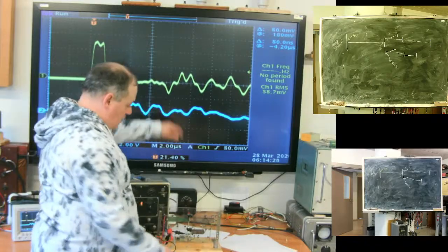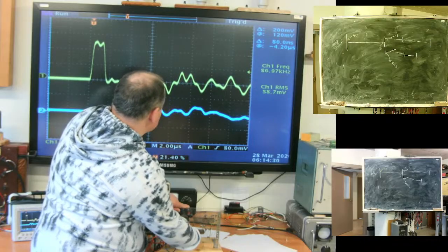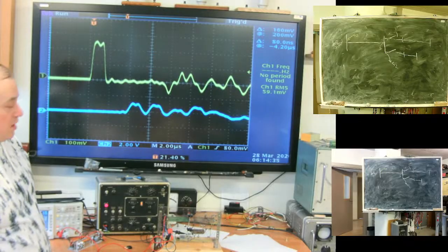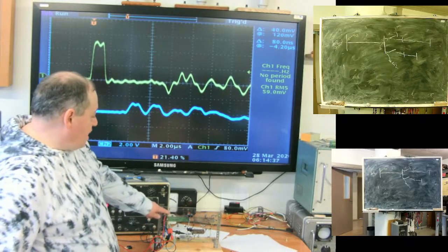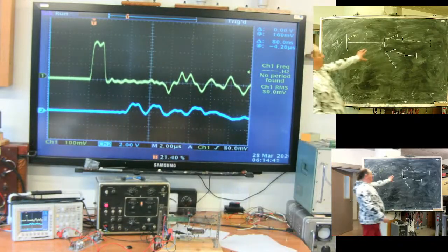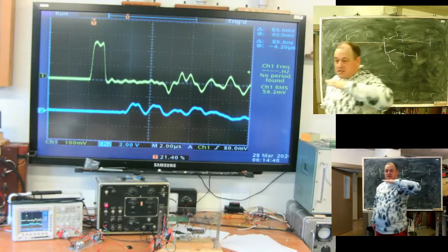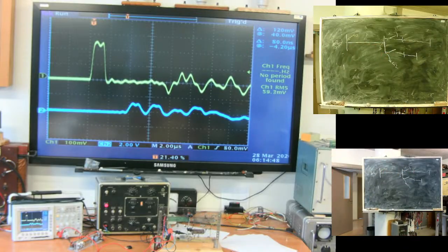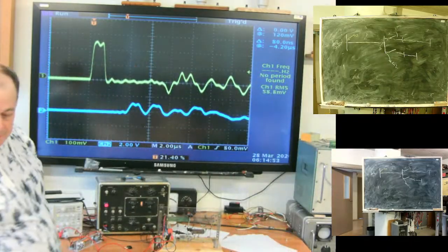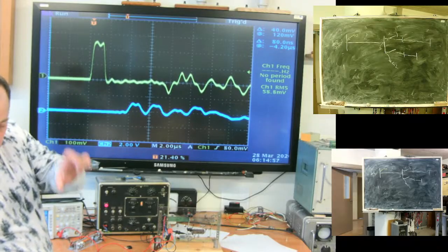Who is this? It's a reflection from the junction point. At the junction point, I have parallel wave resistance. When both switches are on, the wave resistances of these lines are switched in parallel. At this point, I have a transient with a reflection factor for lowering resistance.